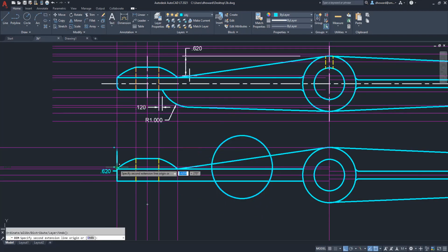I'll show that one more time. I'll dimension that there. There it is. That is the line that I offset. That is the center of this thing. So as far as locating it side to side, they give us another dimension, this 0.12 dimension. And so to do that one, I have to offset 0.12 from the edge of the hole. So the line that created the right edge of this hole, I'm going to offset 0.12. And then I'm going to move this circle from that point of intersection to right there where it ought to go.